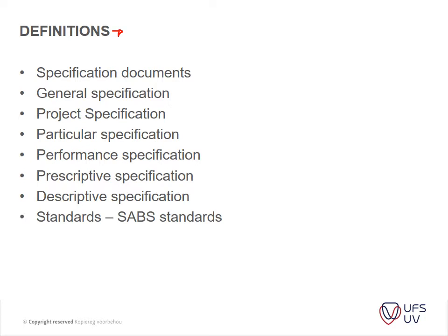You've got your specification documents. Okay, then you have your general specifications. So your specification documents usually comprise different sets of specifications. For instance, the architect might have a specific set of specifications, for instance drawings, finishing schedules, etc., whereas the engineers might have very specific documentation on, for instance, how concrete is tested and what justifies a concrete test. Should it be tested on 7 days, 21 days?